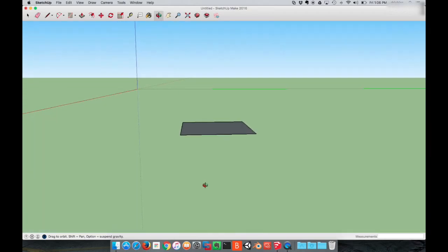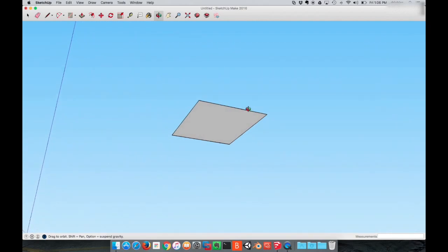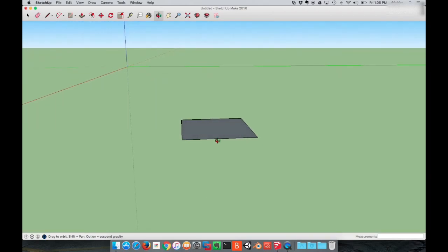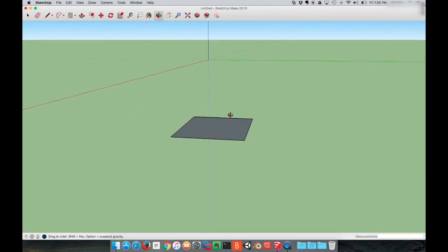SketchUp has one-sided objects. Only one face will show up in printing. The white face is the one that should always face outside, whereas the blue face should be on the inside of your models. You can flip those. I'll show in a later video if you have problems with that.